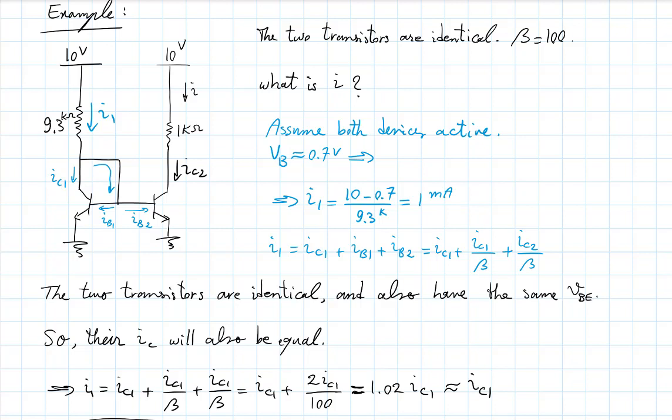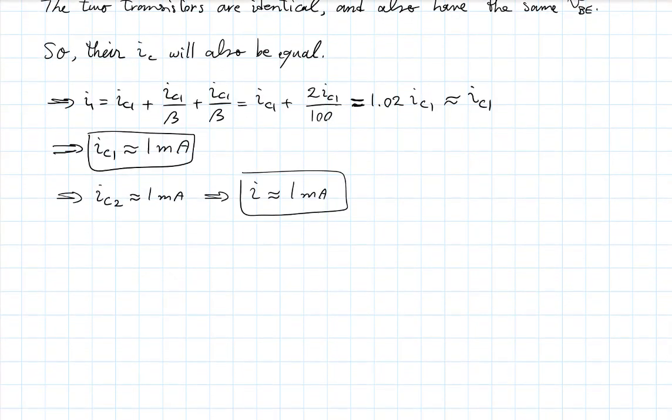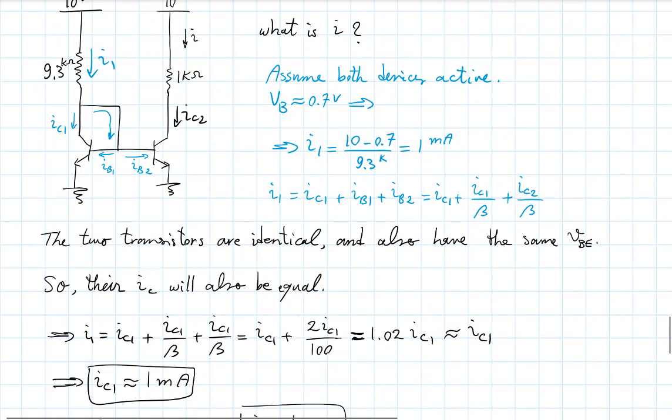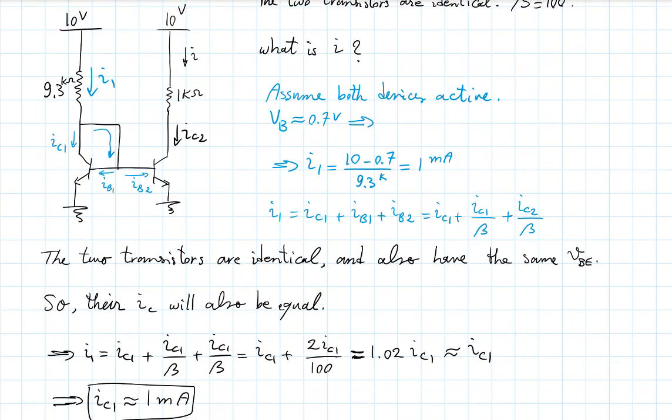What was it in the circuit that made the value of I not depend on the 1 kilo ohm resistor up there? It was this. Look at where we got that current. The way we calculated it was through the transistor current. And the transistor is acting as a current source. Like we said from the beginning when we started this discussion.